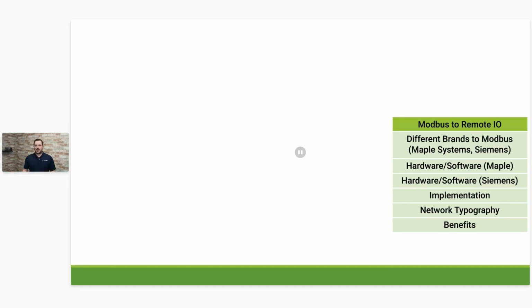So on our end, the limit is just going to be dependent on the PLC brand that you're using. For example, if you're using an Allen Bradley PLC, you'd want to check the specific manual for that PLC, whether you're using a Compact or a ControlLogix or an older MicroLogix, on how many slave devices it can talk to as a master communicator. Because in this case, the PLC will have to act as a master device to communicate with the remote I/O couplers since they are slave-only devices.